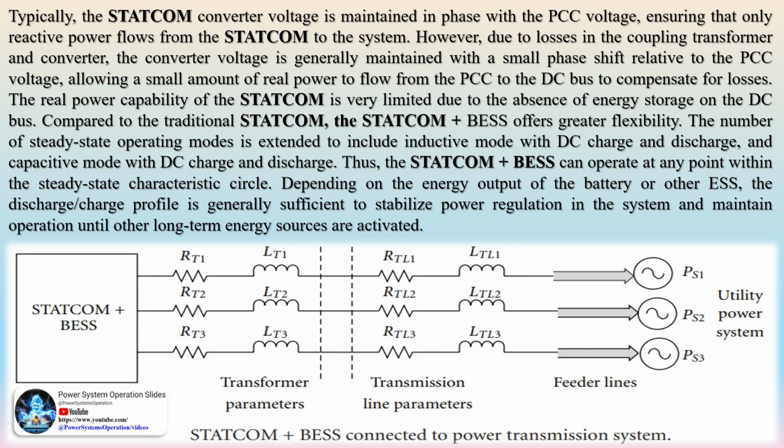During severe disturbances, such as line sag or faults, turbines transmit less power to the grid, causing an imbalance between mechanical and electrical power, which increases turbine speed. This speed increase leads to higher reactive power consumption and voltage dips. Stability can only be maintained if the increased generator speed remains below the critical limit, necessitating external reactive power supply